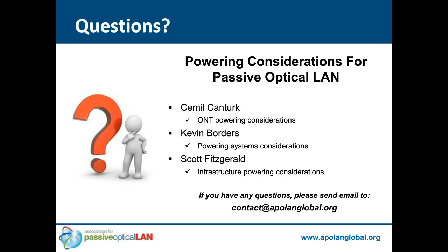Now, the batteries are only going to last for a certain amount of time, and that's going to be dependent on how long you choose to equip them. So it may be 2 hours or 4 hours or 8 hours of backup. In most cases, that gives you ample time to provide a generator, whether it's a standby generator, which would be on present, or a portable generator. So, yes, a centralized plant could take down the network, but it would be a rare condition. And the best example to compare that to would be a central office, which are sort of bedrock. They very, very seldom fail because of power.